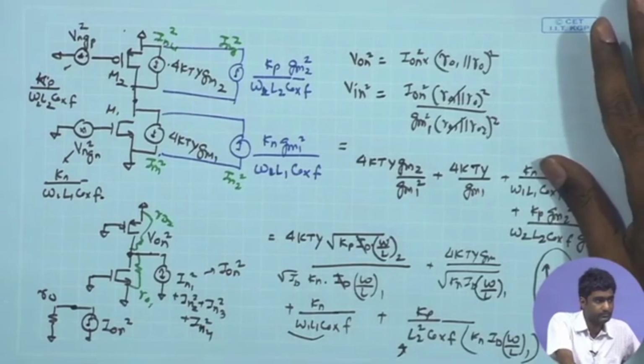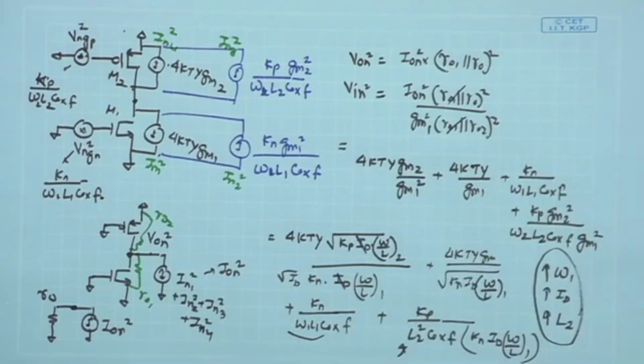Proceed. 1 upon F noise is due to trapping and releasing of the electron, but for PMOS, the gate voltage is not changing or active? No, but there is always continuous activity, so it's not only signal dependent. Randomly also, under equilibrium, you have trapping going on. When you apply the gate signal, it changes that trapping process. But when you have two opposing phenomena going on, trapping and retrapping, it reaches an equilibrium where the trapping and retrapping are equal in magnitude.